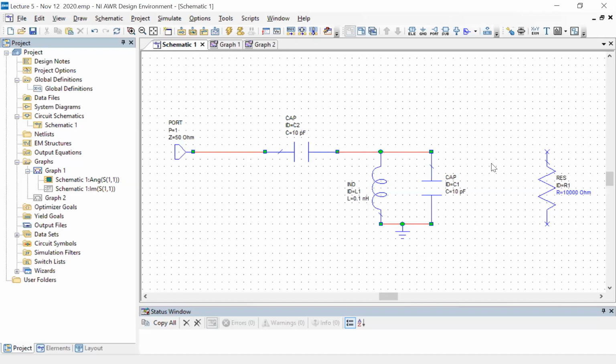Okay. Right. So now we are trying to do the same thing where we are allowing additional circuit elements to control this. And the reason for that could be, as I said, that maybe omega 0 is fixed. Then in order to get different values of ZR so that you can get different values of the Q factor, you will have to change L and C quite a bit depending on what Q factor you want. And then there are practical constraints, which I mentioned, that you cannot have very large capacitances, you cannot have very large inductances. So then you don't have that much flexibility on controlling the Q. So now we are going to look at other ways of controlling the Q.